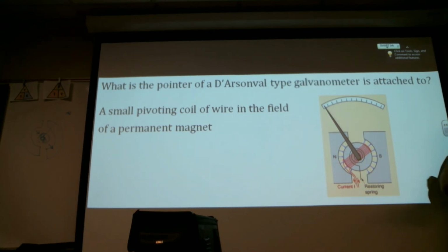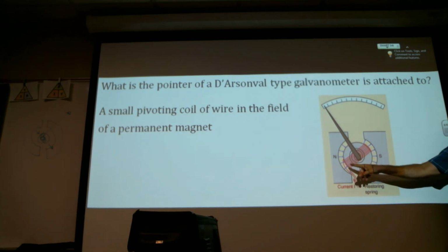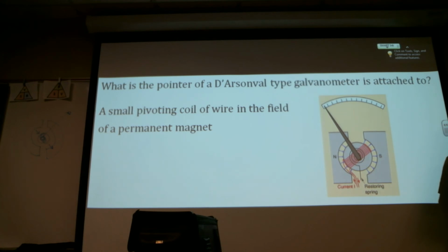It's just that when the voltage, see the red current coming in? Yeah. As we make rotary selectors, if I'm going to measure a 1.5 volt battery, I'm going to make selections on the meter that are going to open up a greater path. If I'm going to measure 1,000 volts, then I'm going to make selections on the meter that are going to really taper it down so I'm not hitting this with 1,000 volts. It's going to restrict it, increase the resistance.